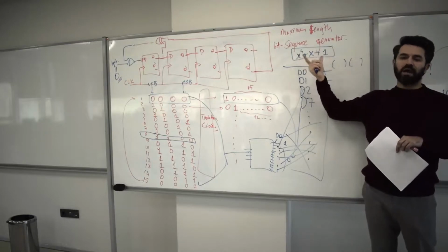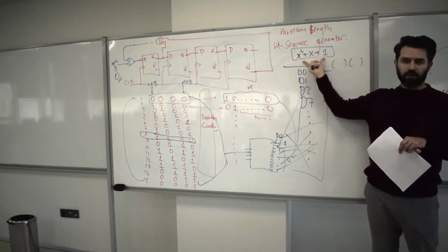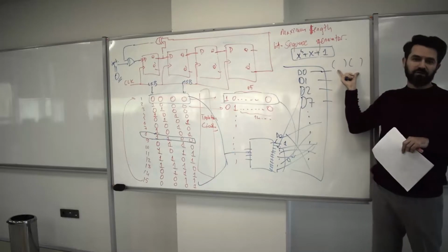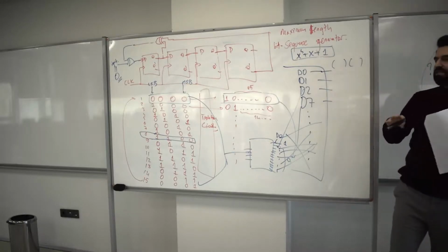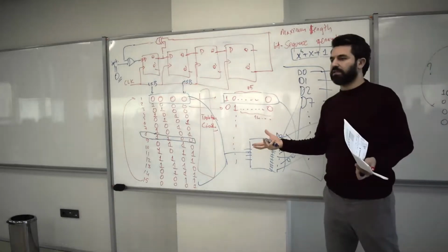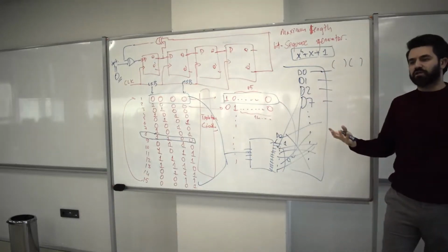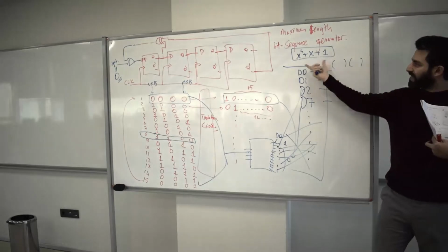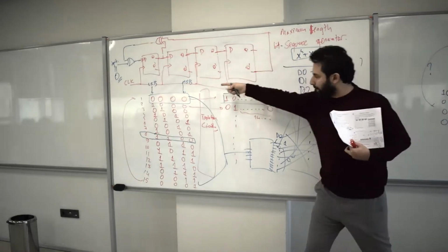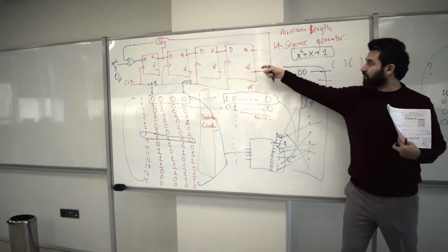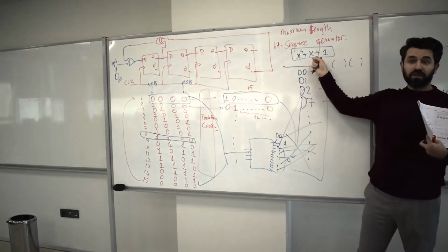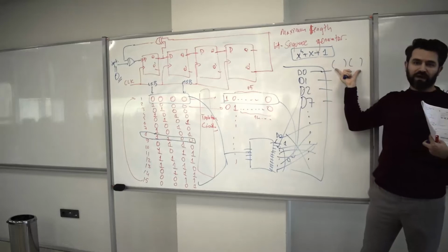In algebra this is called a primitive polynomial, because it cannot be factored into other polynomials. Of course, this is not the major topic of this class. I'm just giving you side information so you can keep it in mind. The reason this generates the maximum number of possibilities is that the representation of this shift register corresponds to a polynomial that cannot be factored.